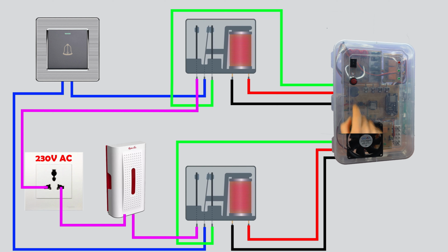When the house owner turns off the doorbell system while at home, the 2 relays are deactivated and the doorbell switch resumes its traditional function. However, when the house owner is away from home, the NodeMCU doorbell system is activated and the second and third relays are turned on. This effectively changes the doorbell switch to the NodeMCU doorbell system trigger switch.